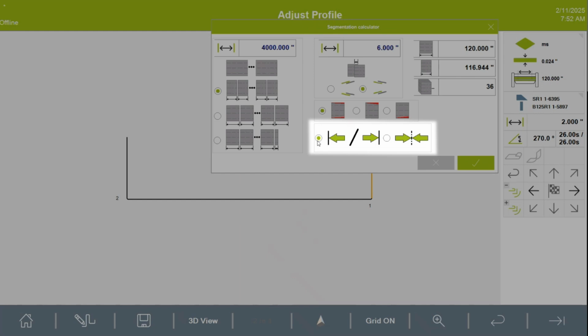Okay, and what that's telling you to do is you need to take the part and move it all the way to the left or all the way to the right hand side of the machine, and you're going to hit the squaring arms. For those of you who've installed a machine with an XTAPER back gauge, there's two squaring arms that come with the machine. One goes on the left, one goes on the right. These are actually your side stops that apply to these arrows when you run the part.